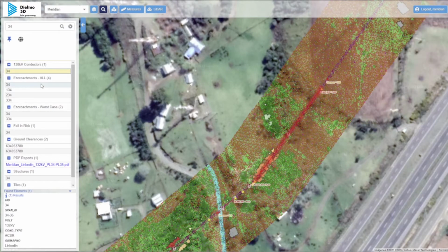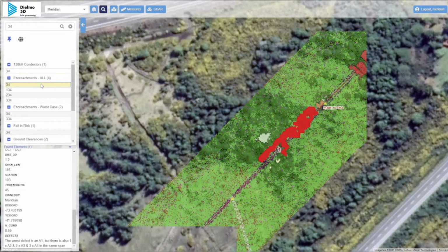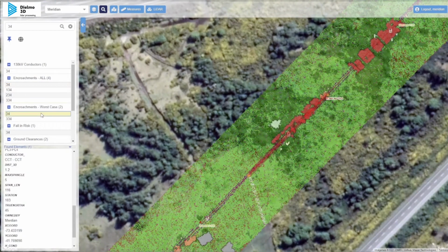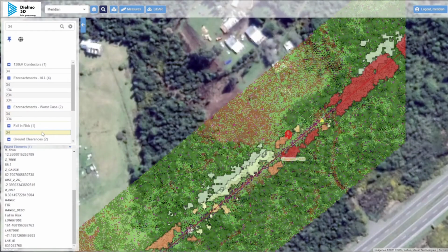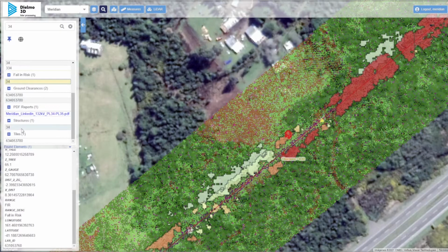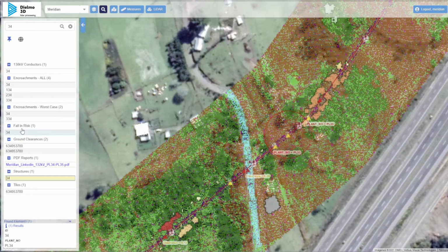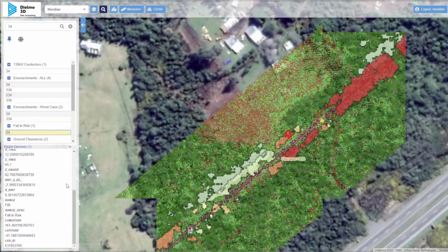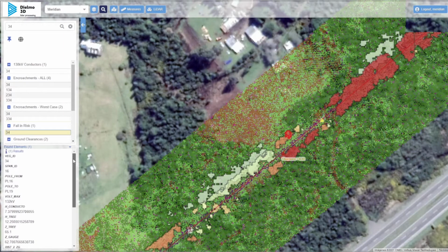The particularity of the geoportal applied to powerline studies is that it makes available to the user not only the cartography, orthophoto, or LiDAR data, but also the results obtained during the study of the network in question. In the case of the treefall study, with a single click on the polygon, we can visualize the level and type of risk of treefall on the study line, height of the tree, distance of the tree from the network, etc.